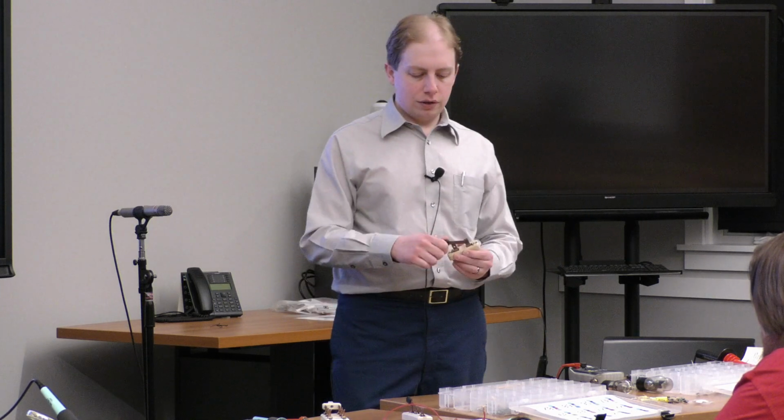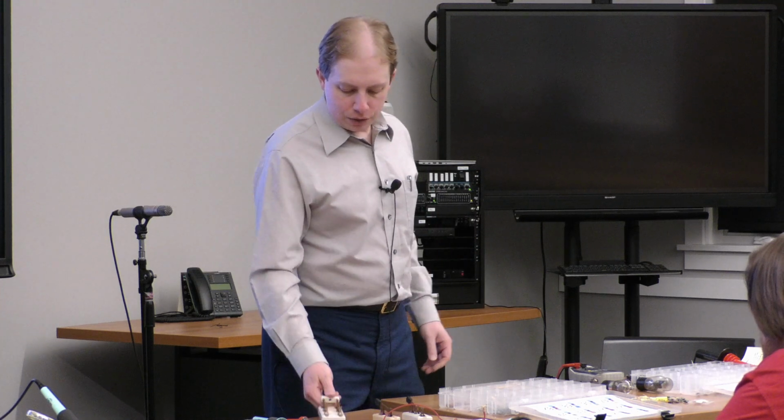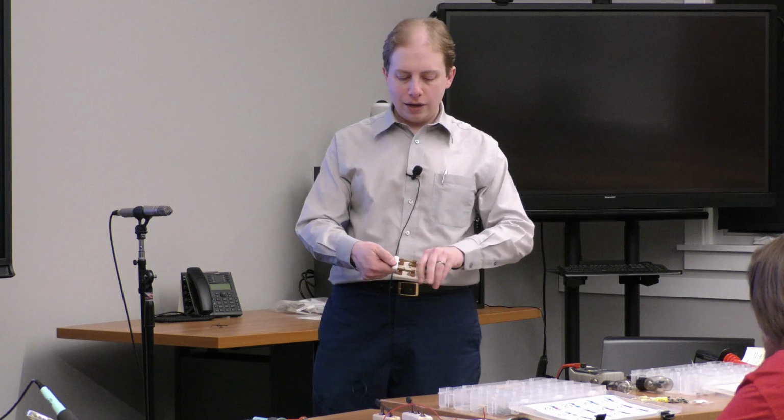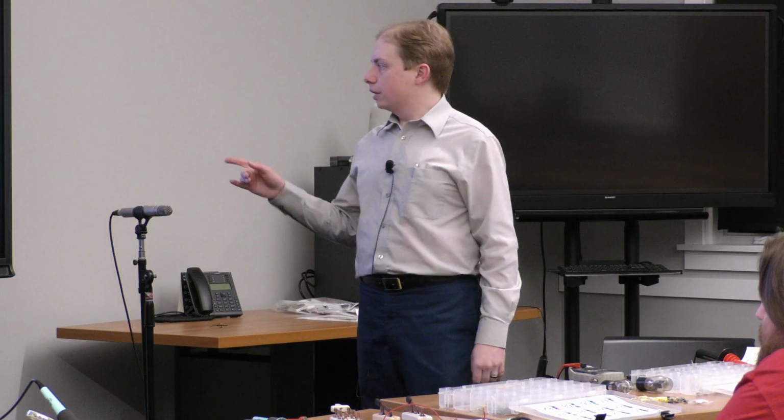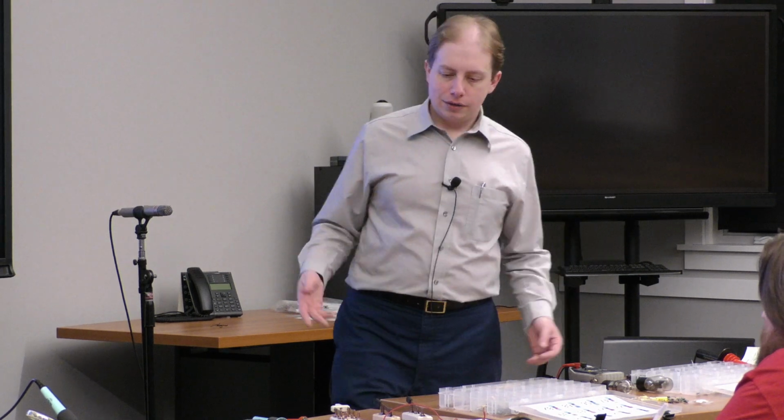And you just have to look at the terminals on the back of the switch to figure out what kind of switch it is. A power switch is usually just a single pole, single throw switch. But let's say that there's a couple different things being switched on and off when you turn that switch on. So maybe you actually have a double pole, single throw power switch. Just some examples. A relay is a type of switch that's controlled by a current. In some ways, that kind of sounds like a transistor, doesn't it? Where you have a small voltage controlling a larger current.